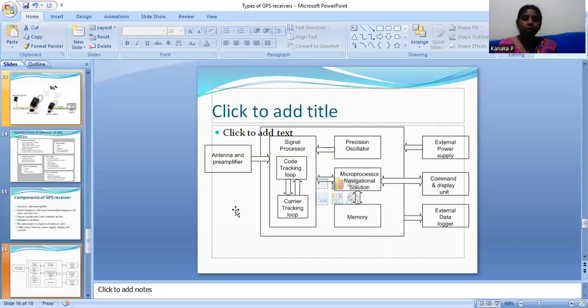First one is the microwave EDM system. Microwave EDM systems are important in land surveying because they are used to measure distances varying from 50 meters to 50 kilometers. The introduction of GPS has reduced their use. The system consists of a master set up at one end of the distance, and the remote is established at the other end.